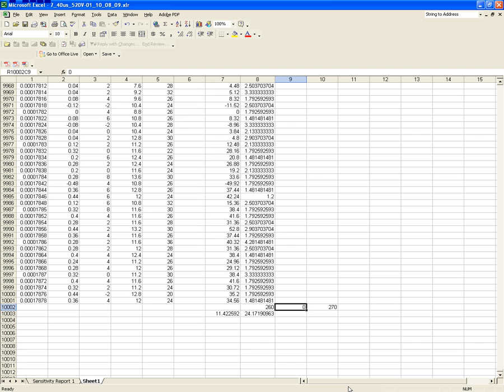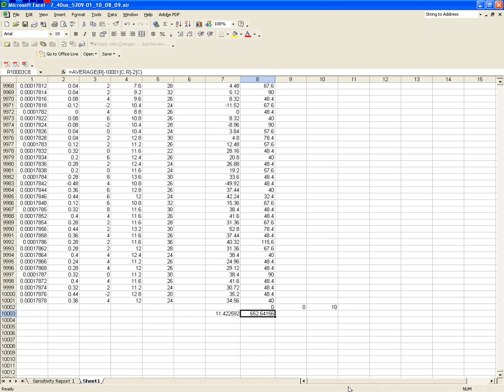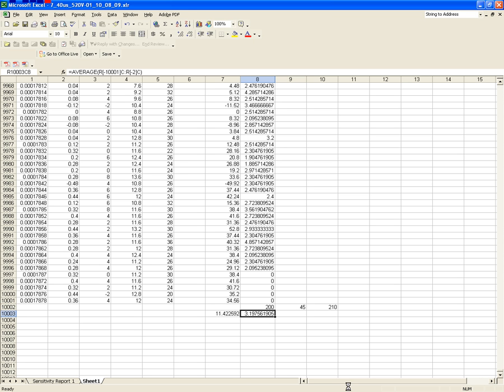If we were at 0 degrees, which we know we aren't, and we had no inductive impedance, then we'd have 655 or 652 watts. But we know that we're not at 0 degrees. We know that we're at least 45 degrees, and we know that we have at least 200 ohms of inductive impedance, which puts our output wattage well below our battery wattage in this case.